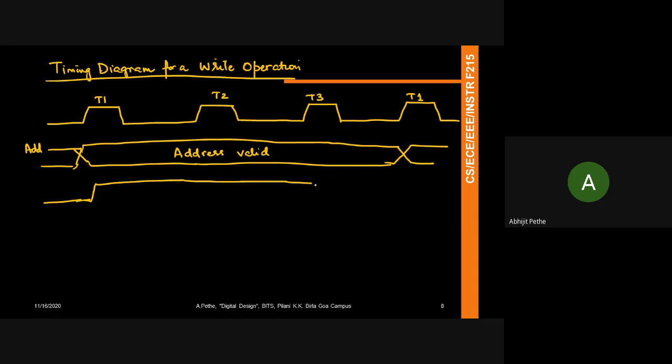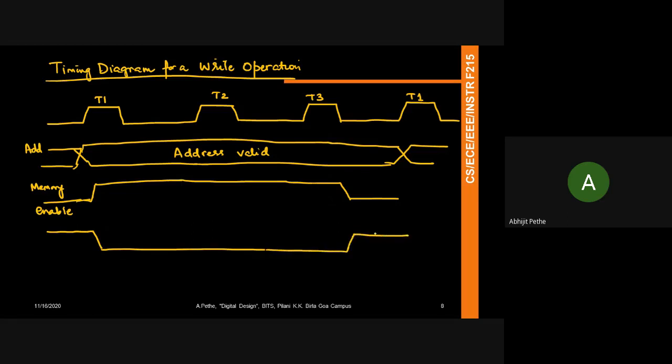And when I disable them, let's assume that I have to generate a timing signal, right? So normally, I'm showing you what a typical timing diagram would look like for a write process. So I would say memory enable, I will give it a high during this process. At the same time, I will give a low on the read write bar signal. Right? And if I look at the data output, right?